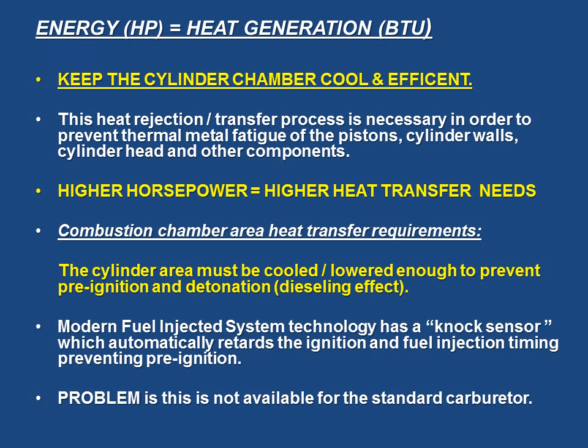Energy equals heat generation. Keep the cylinder chamber cool and efficient for performance repeatability. This heat rejection or transfer process is necessary in order to prevent thermal metal fatigue of the pistons, cylinder walls, cylinder head, and other components. You see, when the metal gets hot, the pores open up. When it's cold, they're closed. So if we can, in the slightest percentage of way, maintain a consistency, it's a good thing.